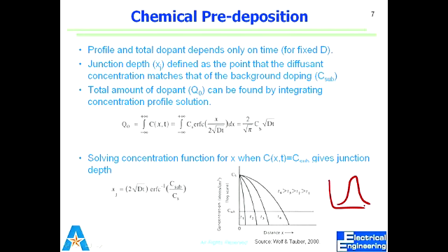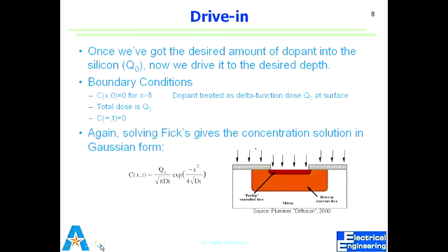So if I want to control junction depth and have this in a source or drain instead of an embedded profile, I can control the beam and have this peak on the surface. So I get something like this, which is very close to the surface. We'll get to that.